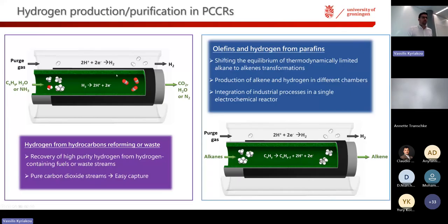Of course, if you have a ceramic membrane, so you have two different chambers that are sealed, you can extract hydrogen from a mixture at any moment. So there are different applications. One very interesting one for the future has to do with biogas steam reforming. If you supply biogas or ammonia on this cermet of nickel BZCY, the material helps as a catalyst. You are producing hydrogen, which can be converted to protons, and you can extract pure or almost pure hydrogen on the second side, the cathodic side in such a case.